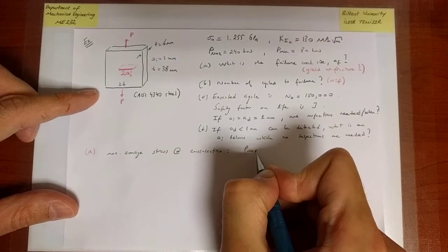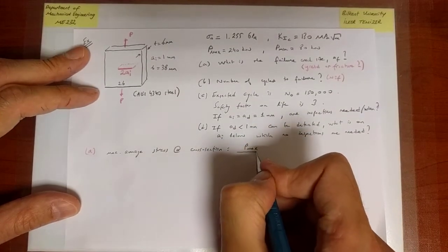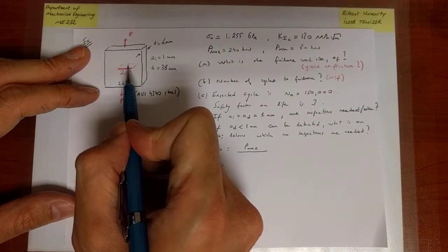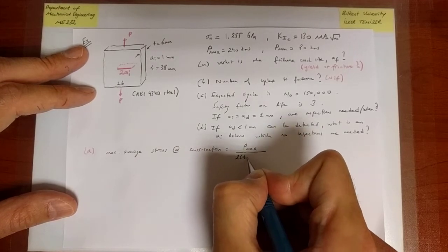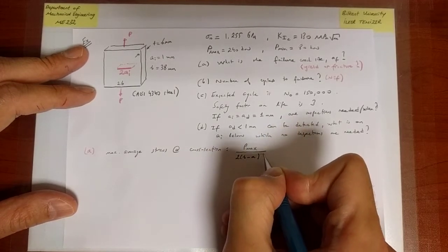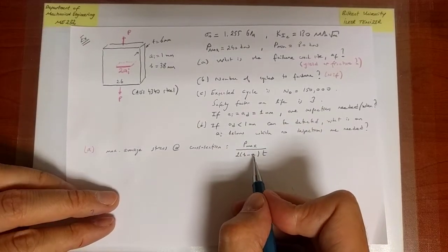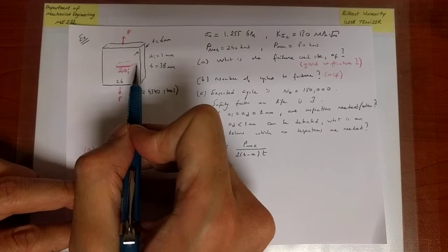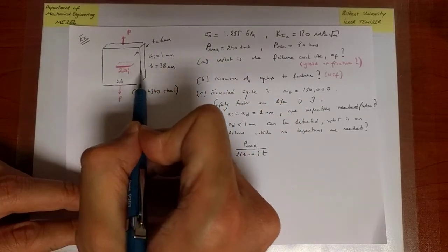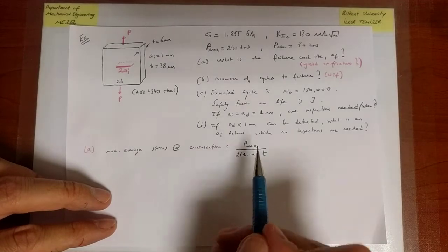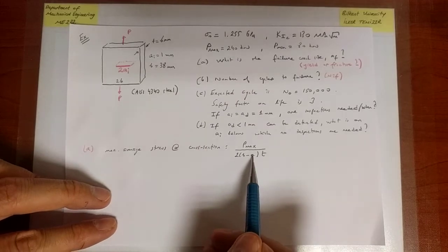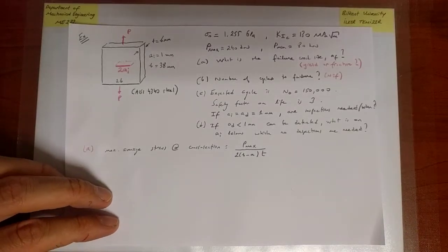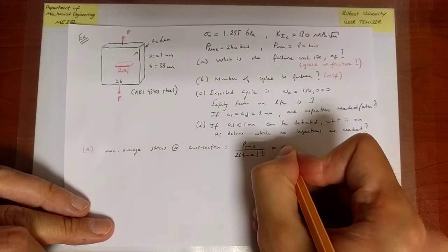Pmax divided by the area at that cross section reduced by the presence of the crack. Remember, we're just looking at the average stress. So for sure, locally there will be yielding, but with respect to the yield criterion, we're interested in the yielding of the whole cross section. Okay. Now, this is the maximum average stress at the cross section where the crack is present. Area is reduced by the presence of the crack. And if the crack is large enough, then failure will occur through yielding.